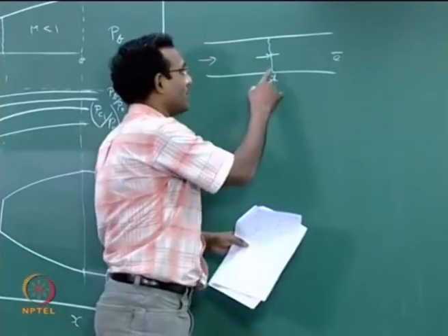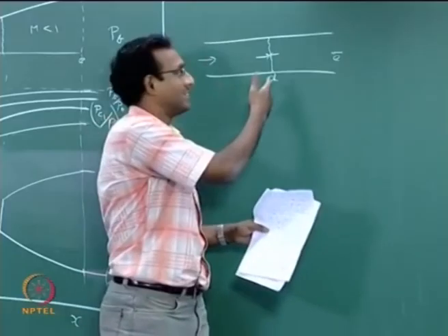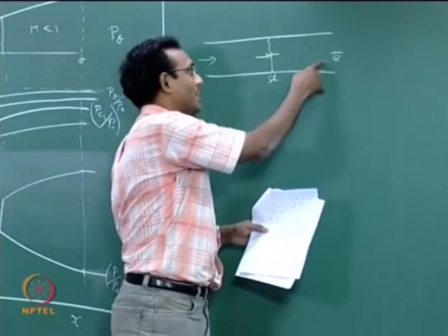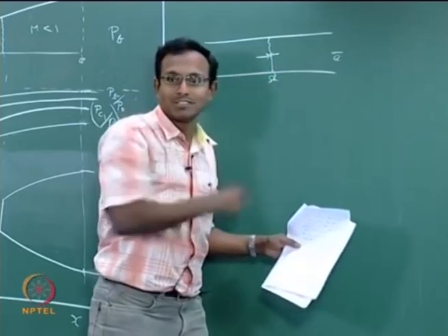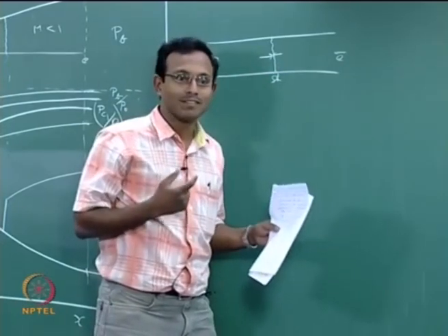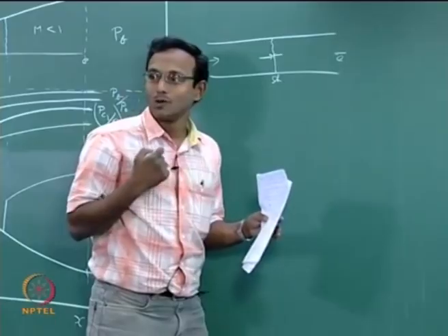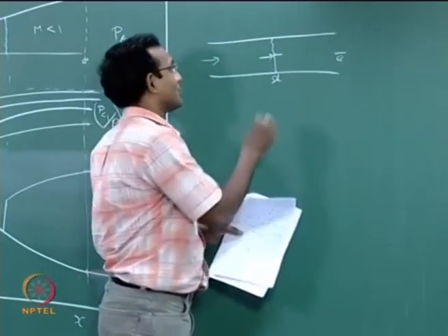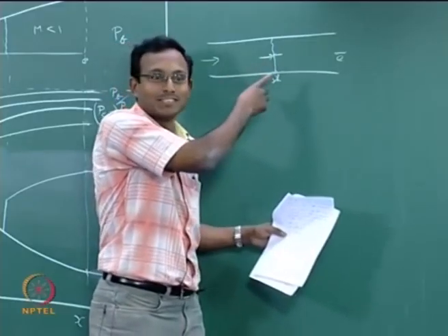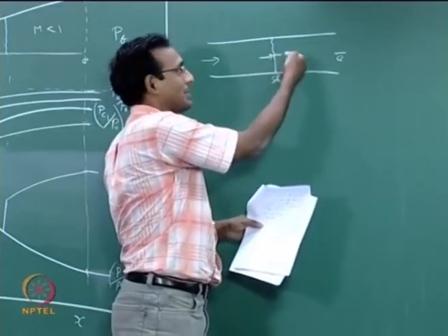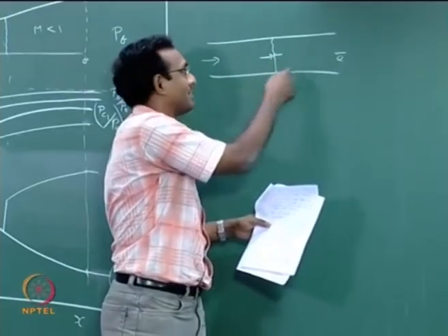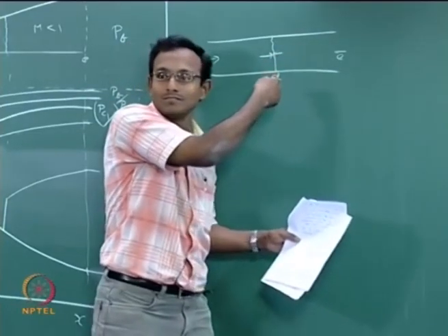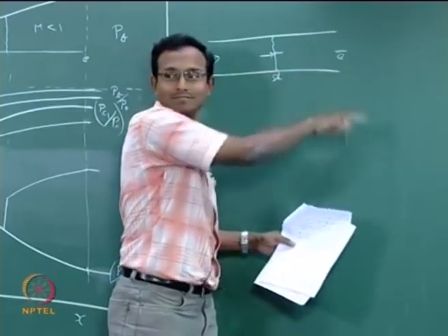All the compression waves, the last wave alone will be negated by this expansion wave, right? There are so many waves. Let us say there are 100 waves inside that shock. I sent one expansion wave inside, now it is only 99 waves, not 100. So that moving shock is now going to go slow, because one wave less. Treadmill problem, easy to understand. The treadmill speed remains the same, but the guy running against it is running slower, so he will go that way. Okay.